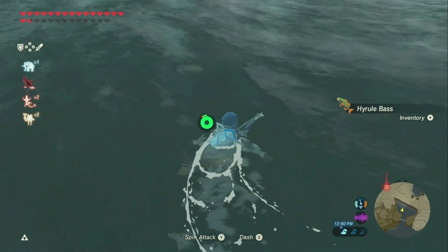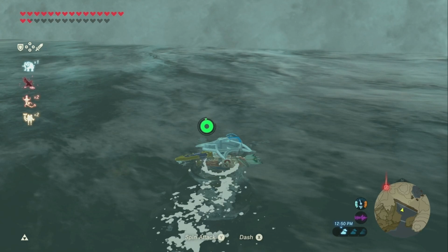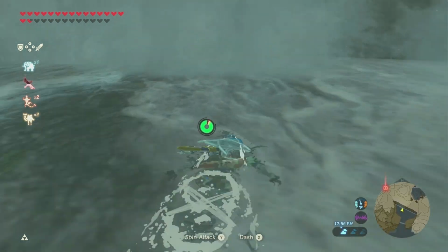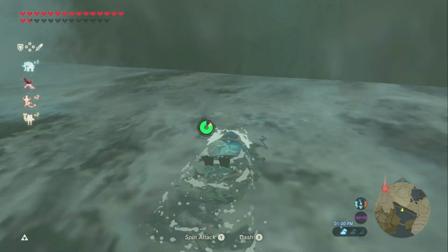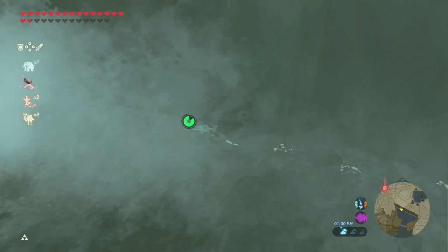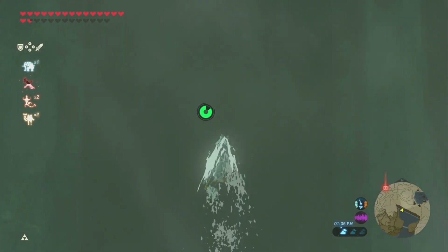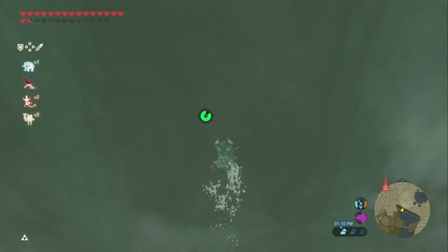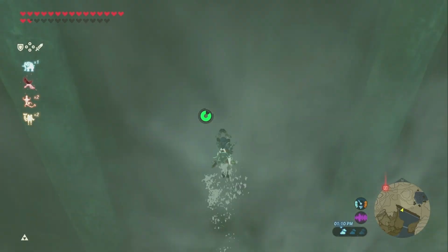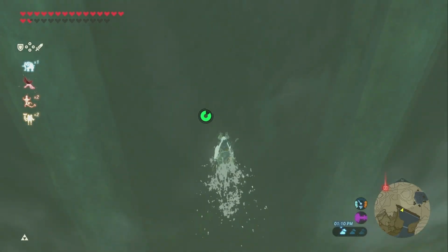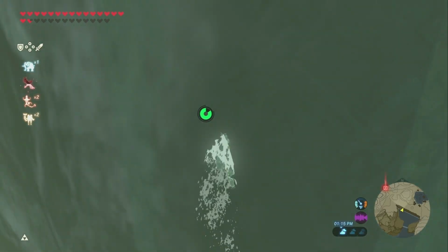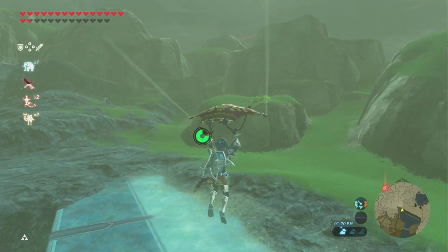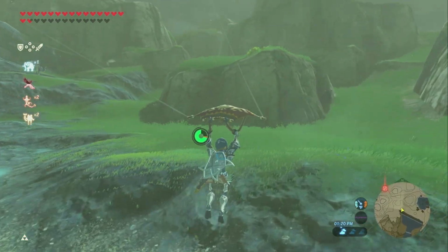High efficiency water heaters and space heating. High efficiency water heaters, and some conventional efficiency units, heat not only the domestic hot water, but also the home itself. The unit has a very large BTU input capacity, 100,000 BTUs per hour, for example. Potable water is borrowed from the domestic water heater to heat the house. This can be done through a number of systems.